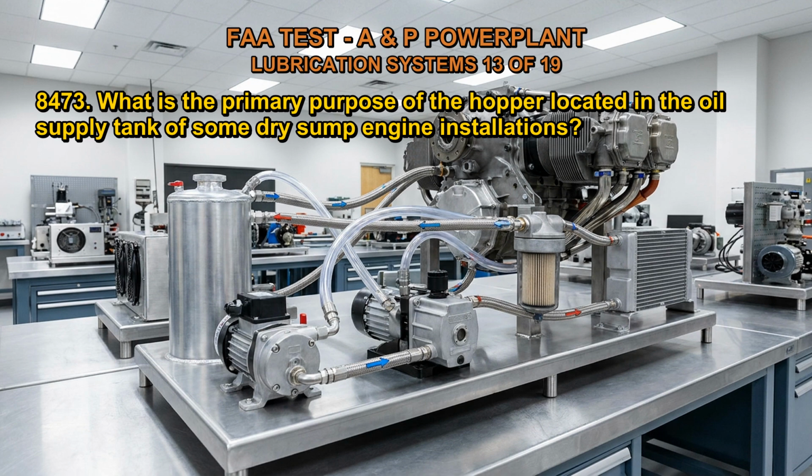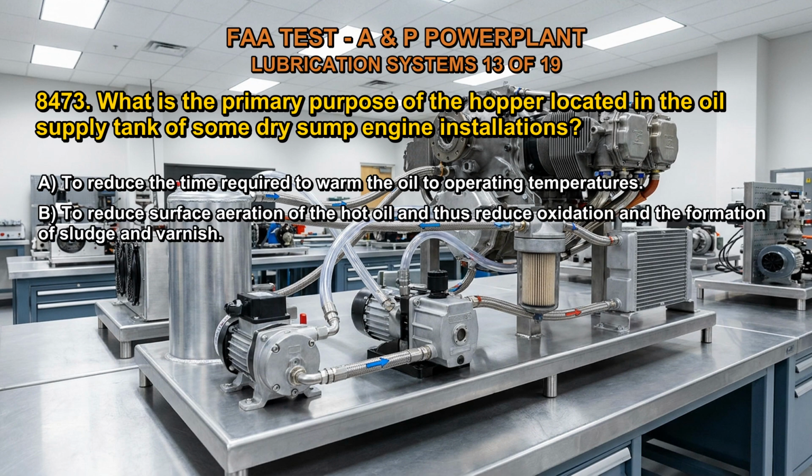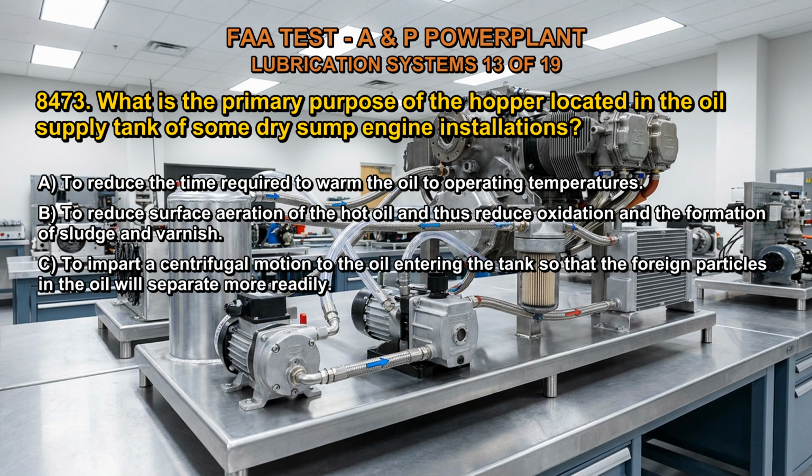8473. What is the primary purpose of the hopper located in the oil supply tank of some dry-sump engine installations? A. To reduce the time required to warm the oil to operating temperatures. B. To reduce surface aeration of the hot oil and thus reduce oxidation and the formation of sludge and varnish. C. To impart a centrifugal motion to the oil entering the tank so that the foreign particles in the oil will separate more readily.